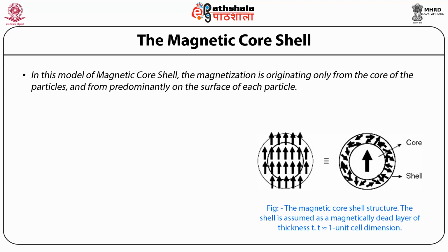In case of nanostructured magnetic material, a significant reduction in saturation magnetization is observed. Therefore, an extremely large magnetic field is usually required for saturation of the magnetization in the case of nanomagnetic particles. The possible explanation for the reduced magnetization of nanoparticles is the core-shell morphology of nanocrystallites.